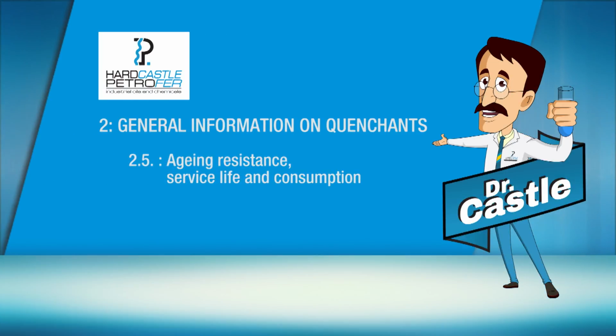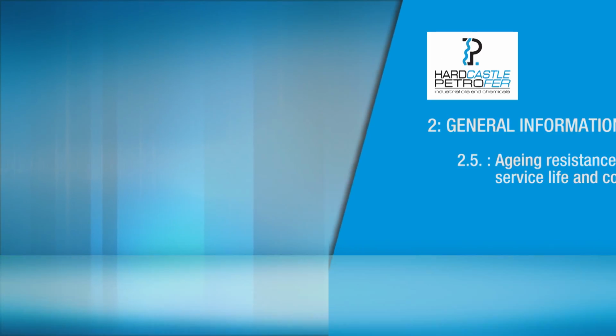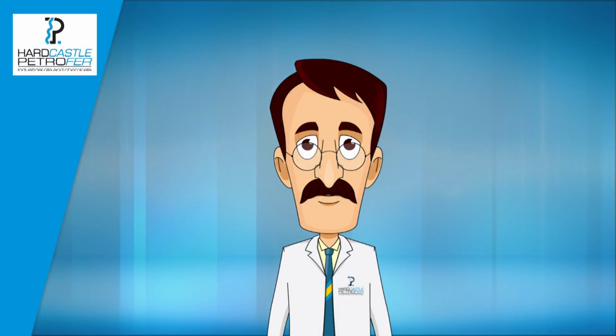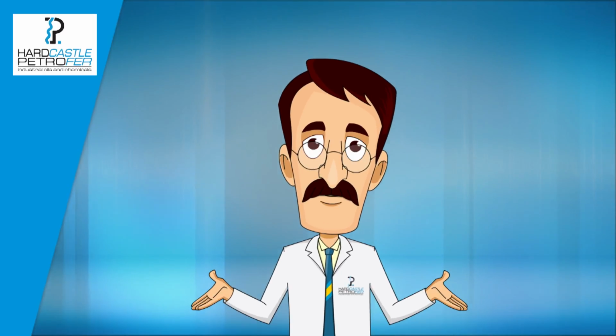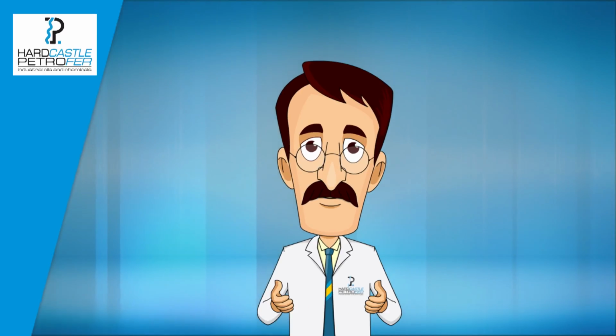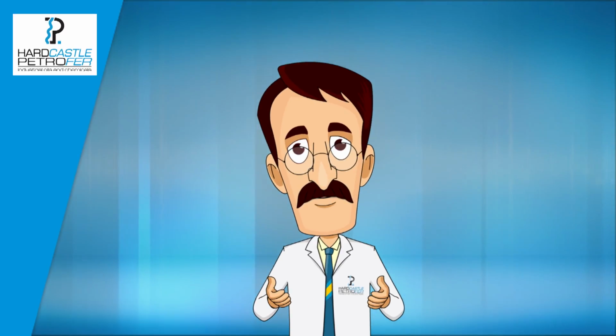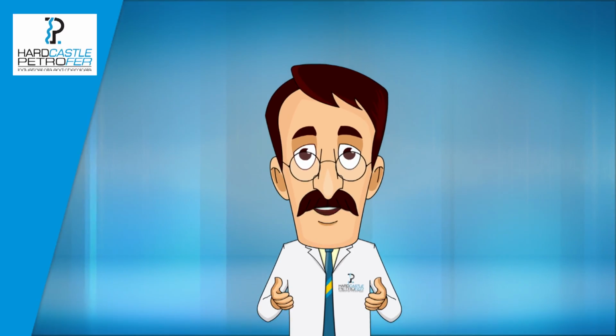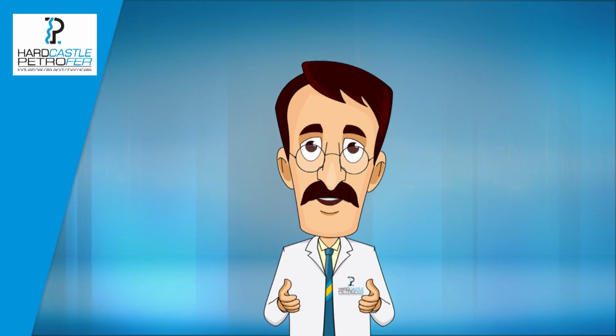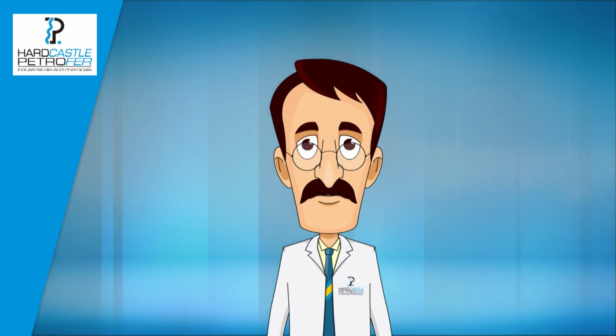Now let's move on to a discussion on the aging resistance, service life, and consumption of quenchants in the process. Resistance to evaporation has a considerable effect on consumption and thus on oil bath economics. Experience has shown that on batch quenching, probably more oil is lost through evaporation than through drag out by the components.